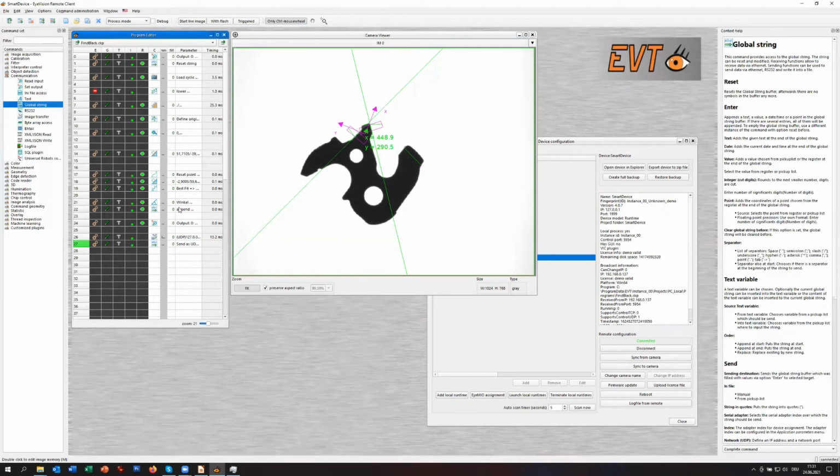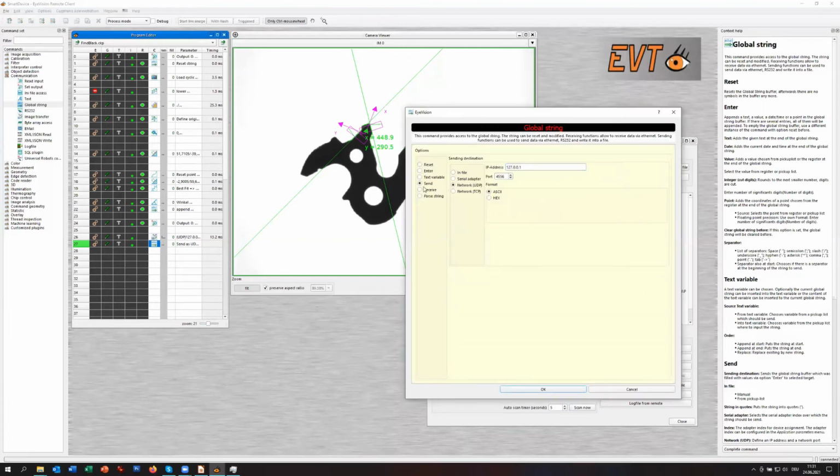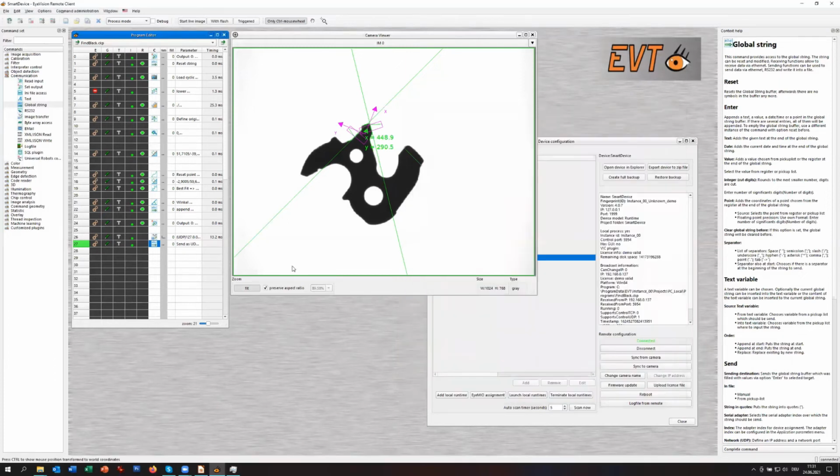So of course, if you have this COM port here, then you select the serial adapter, serial interface. Maybe you have a Profinet anywhere, a Profinet PLC. You are free also to use the Profinet on this remote device. That means after you have programmed and finished with programming all the communication, the resulting values, you don't have to use the PLC I/O of the camera.